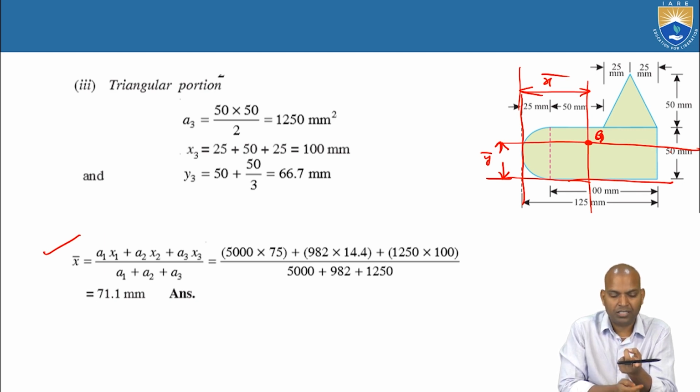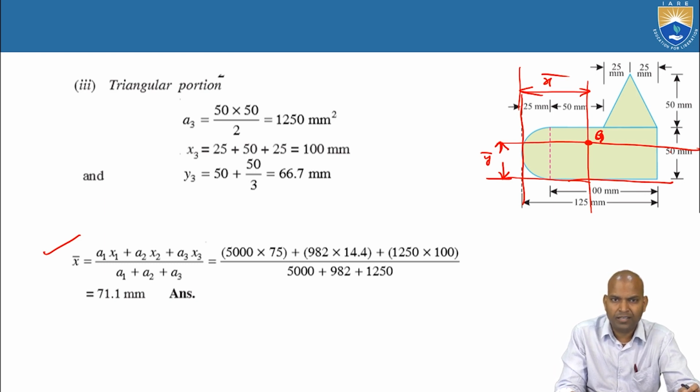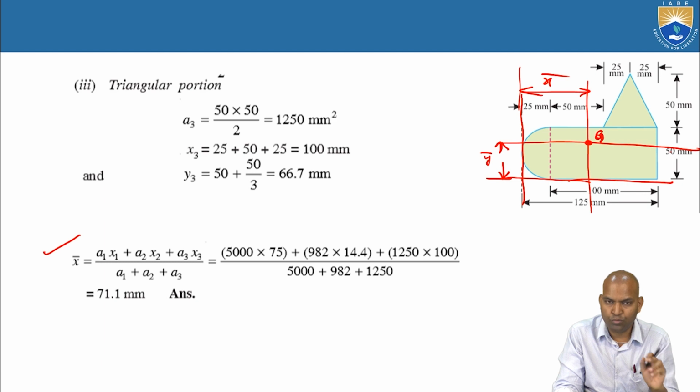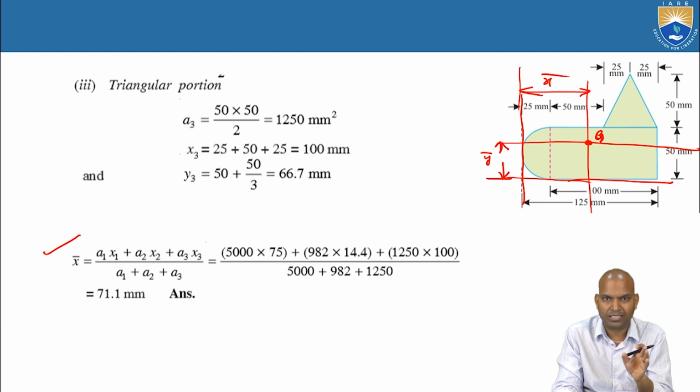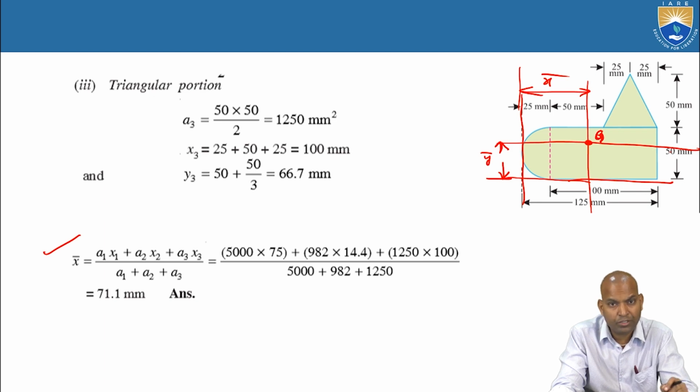It becomes unbalanced when the support is shifted away from the centroid, either towards the left side or the right side. So it's a very important concept in the case of automobiles, where the wheel must be completely balanced. Because of wear and tear, unbalancing takes place, and that unbalancing is corrected in automobile front wheels or railway wheels by using small weights at different positions on the circumference of the wheel.